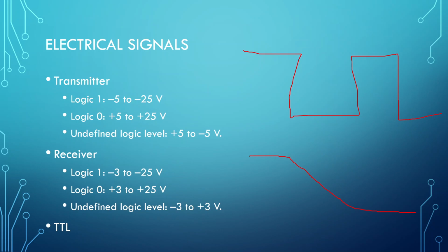Now, it's not going to be as bad as my drawing, as slow. I don't have a time frame on this. It isn't over 1 second that we have this drop. No, it's going to be a millisecond or so. But there is still going to be a plummet there. So it is important to recognize that it actually goes from one state to an undefined state to the other state whenever we transition. It's always going through that. It's not instantaneous.